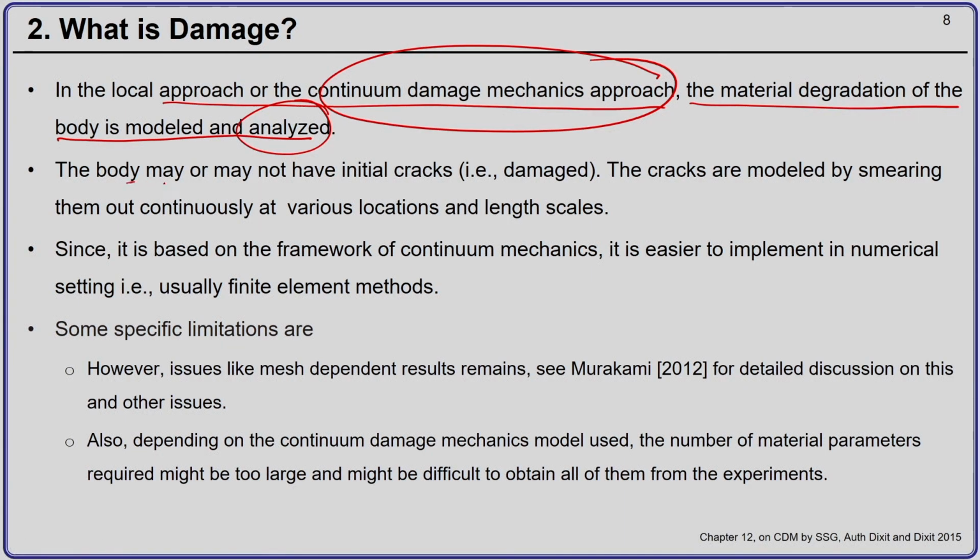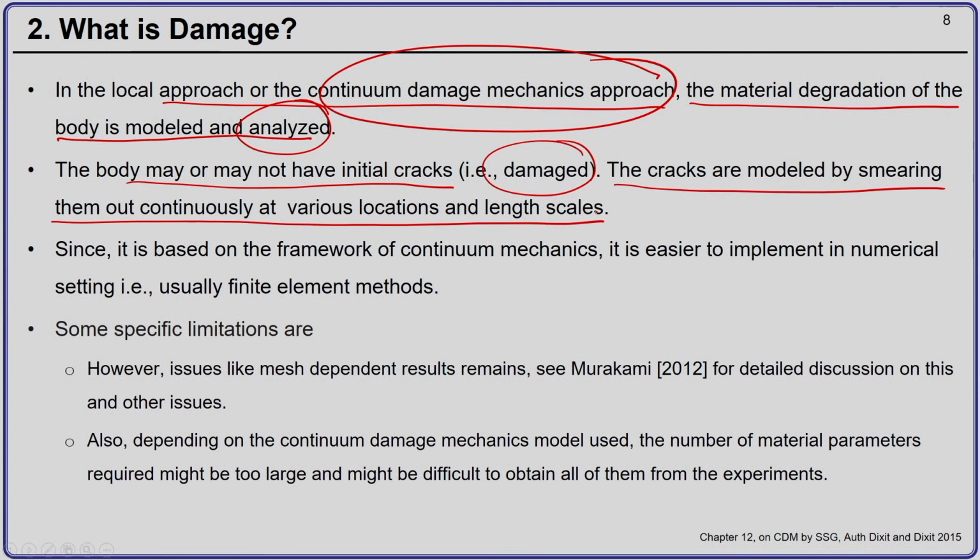So, the body may or may not have an initial crack, that is, it may or may not be damaged from the start. The cracks are modeled by smearing them out continuously at various locations and at various length scales. As the deformation progresses, you will have certain criteria which will originate new cracks where there was no crack initially present.